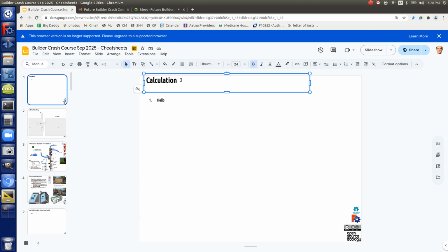Say you got that post right there. How much can it hold? Say it's a 4x4. What do you got? 12,000? How do you get that? 3,000 times 4. Where are you getting 3,000? I think it said 2,000 PSI. Well, 300. 300 to 1,000 for plain wood. 4 inches square, 4x4, 16 square inches.